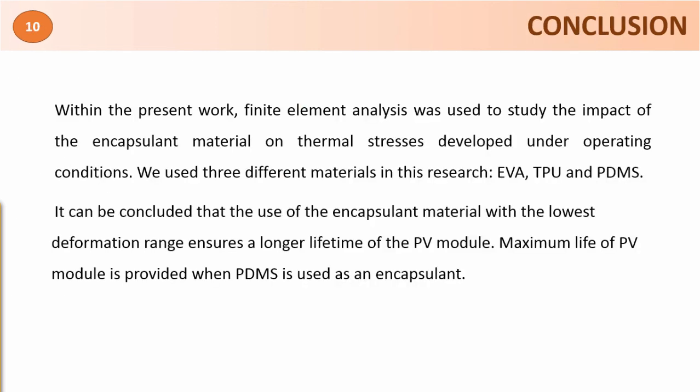Conclusion. Within the present work, finite element analysis was used to study the impact of the encapsulant material on the thermal stresses developed under operating conditions. We used three different materials in this research: EVA, TPU, and PDMS. It can be concluded that using the encapsulant material with the lowest deformation range ensures a longer lifetime of the PV module. Maximum life of the PV module is provided when PDMS is used as an encapsulant.